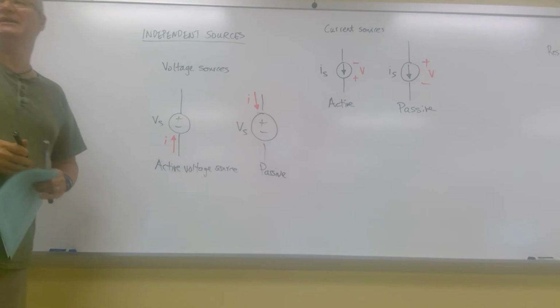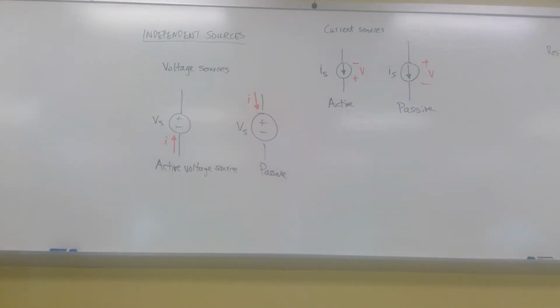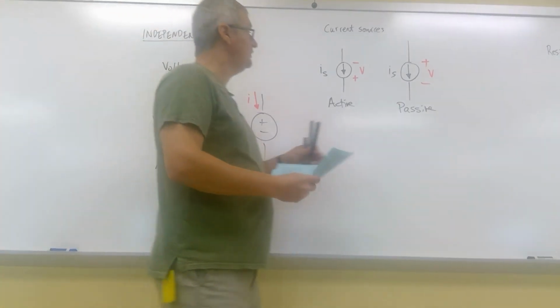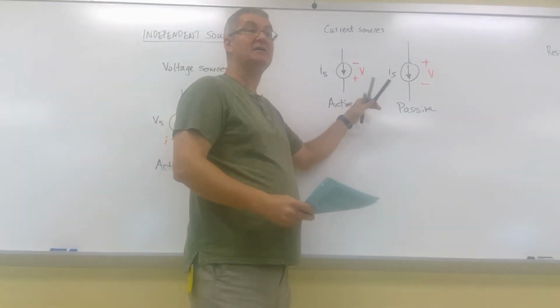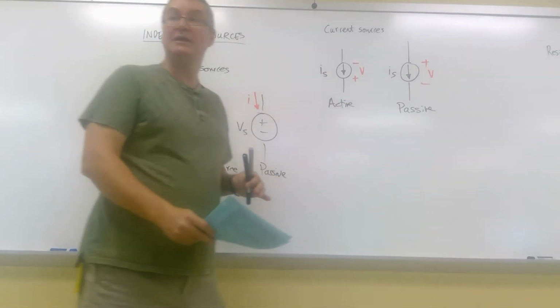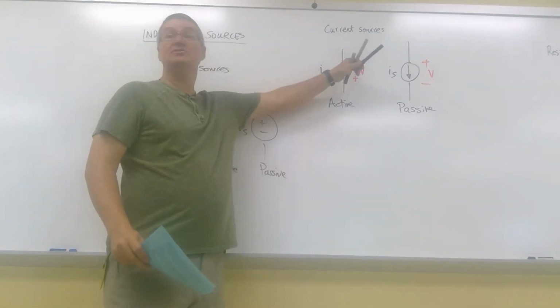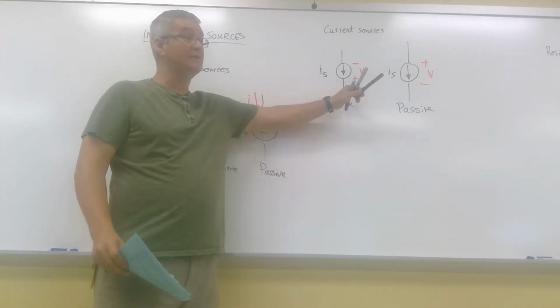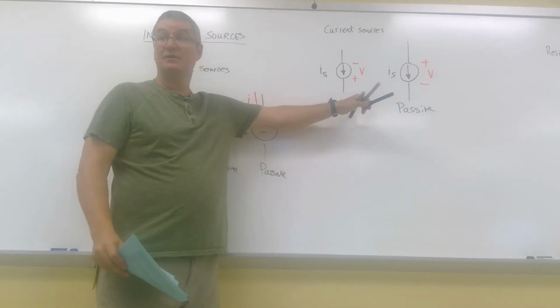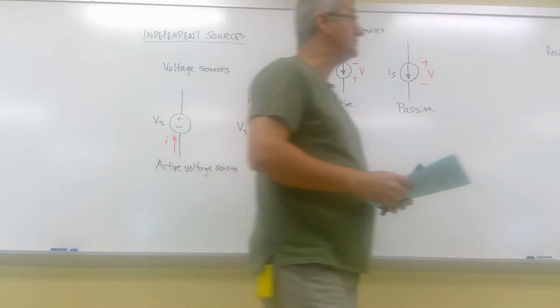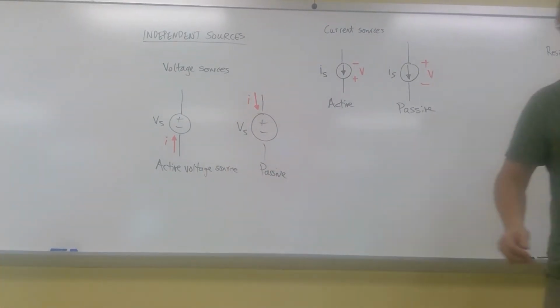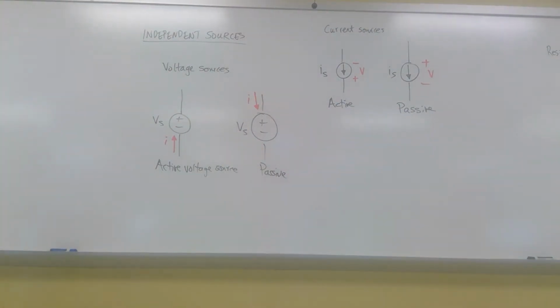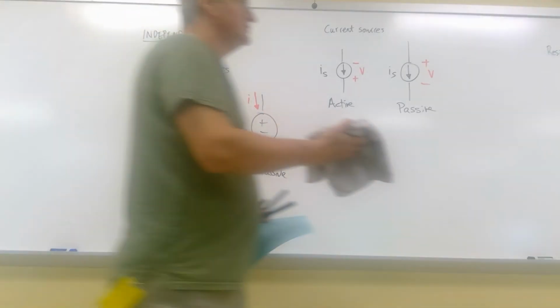This becomes pretty important in chapter 4, by the way. Okay, this is a really simple thing. Look at this sign convention and remember what we mean. Coming in through the negative terminal, it's got to be active. Otherwise, it's passive. And that's a very slippery thing that students seem to not internalize until it's in your face a couple of times.